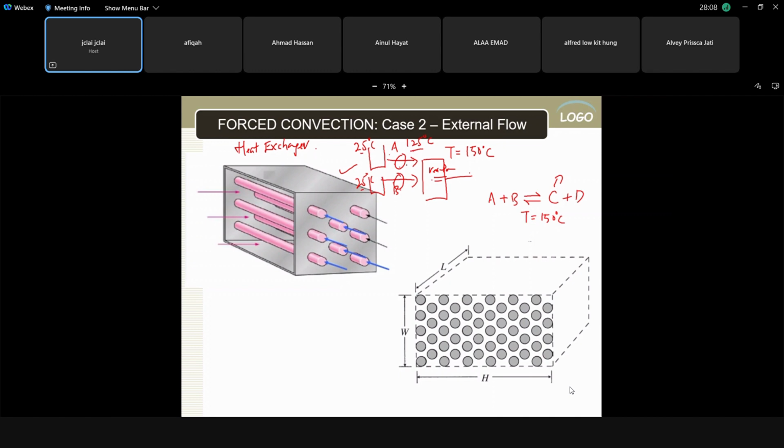Okay, before the raw material is pumped into the reactor. This is where you need a heat exchanger. Okay, let's say here, this is your A or your B. Okay, your raw material here. Then here you have steam or hot water. Hot water cannot. In this case, it should be steam. Okay, steam. So steam goes through the pipe here.